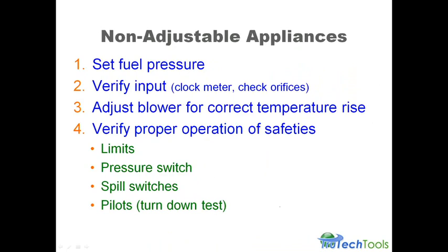You need to verify the input. That means you need to clock the meter. You need to know what the heat content is of the gas. You need to clock the meter. The directions are in with the furnace manual. And clock the meter and make sure that the input to the appliance is correct.